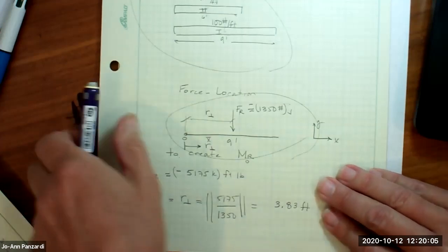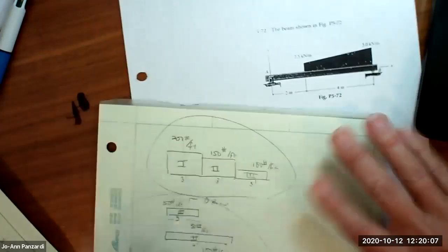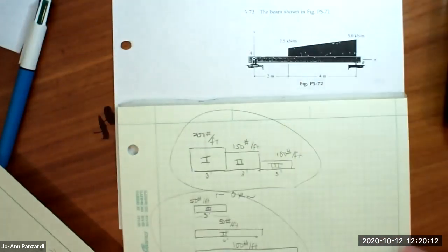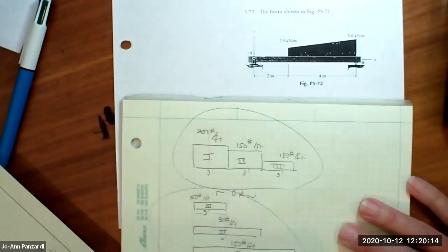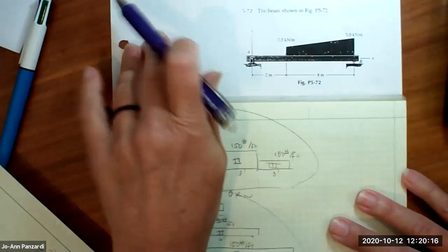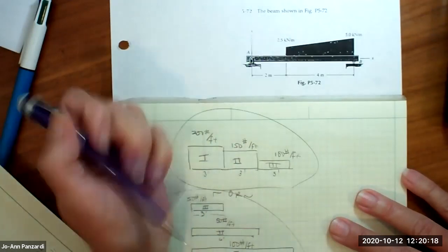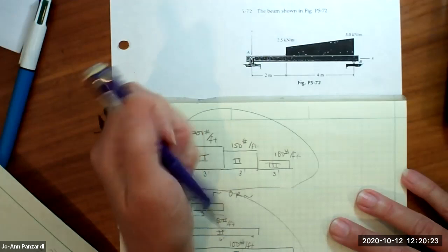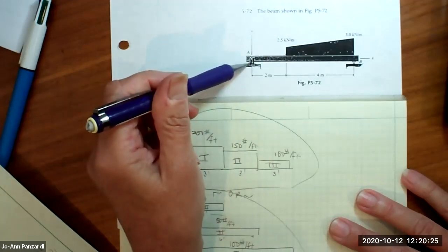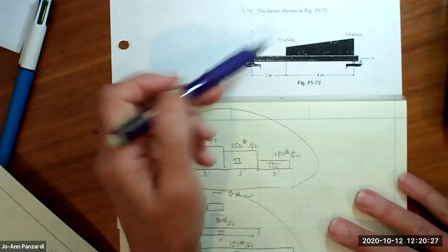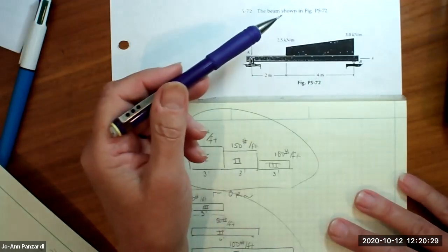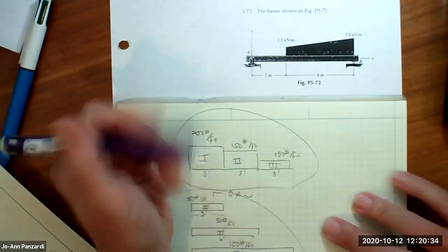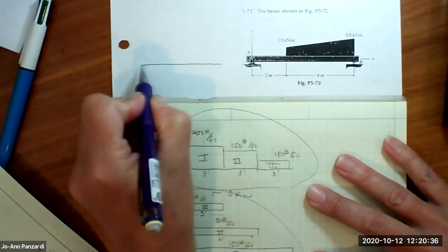If you wanted to look at another problem, here's another problem. It's a trapezoid again. Again, my suggestion is to split it up into a triangle and a rectangle. So you would have two forces at a certain distance from point A. And then you need to find the resultant force, the resultant moment about A, and find the perpendicular distance. And I'll tell you what that answer is too.